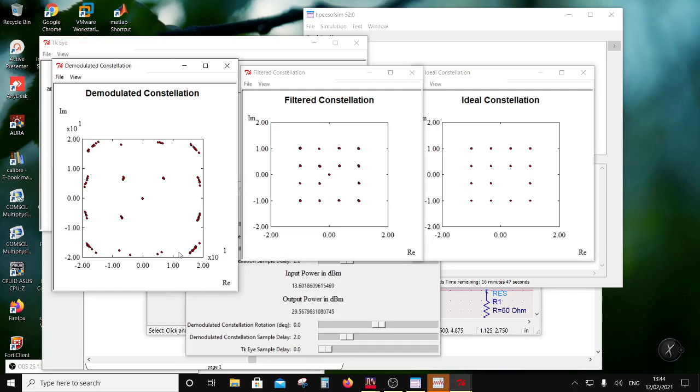Now there is no PM data here, right? Whatever phase rotation you are seeing is because of the phase noise of the VCO. But then the PA is also going to give you the rotation if there was a phase information in the model along the power, right? So in that case, you would have seen the rotation of the demodulated constellation also because of the PA.